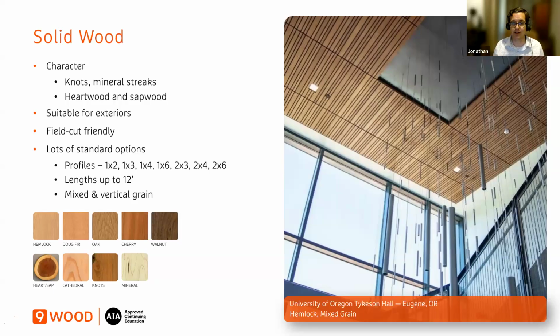If you've seen cedar, maybe at Home Depot, it has a lot of color variation from very light blonde to dark brown colors and everything in between, which can be exactly what you want, but it really depends on the design intent and maybe client expectations. If you want to control or better dial in the natural color variation, the first decision is to choose the right species. Make sure you get all the samples, ideally even photos of installed spaces with the species and project you're looking at, so you can get a good perspective early on of what that variation is going to look like, and you can make an informed decision.